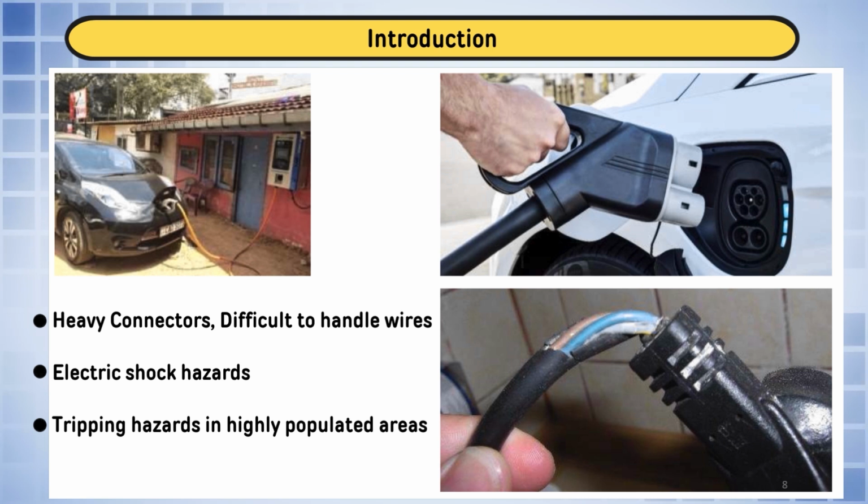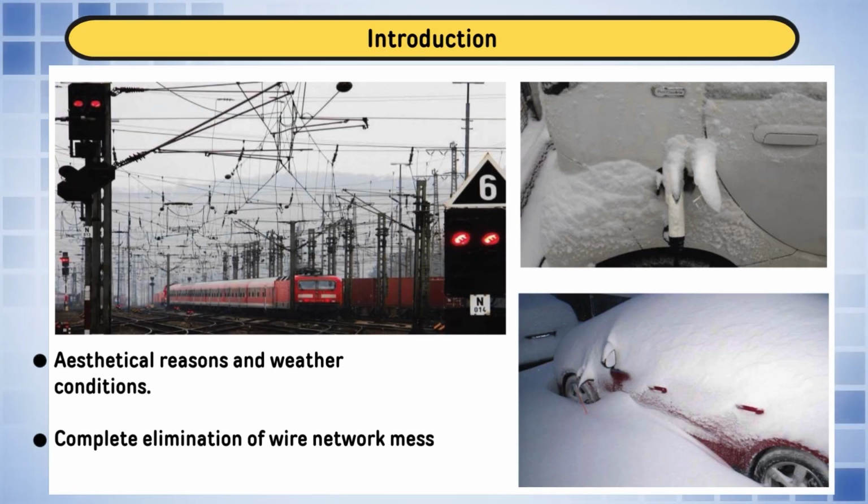So, these DC-DC converters are utilized in case of wind power conversion units, in case of photovoltaic systems, in case of fuel cells, where these DC-DC converters can be used to do the MPPT, maximum power point tracking. So, one algorithm is utilized. There are n number of algorithms which are available to achieve the MPPT.